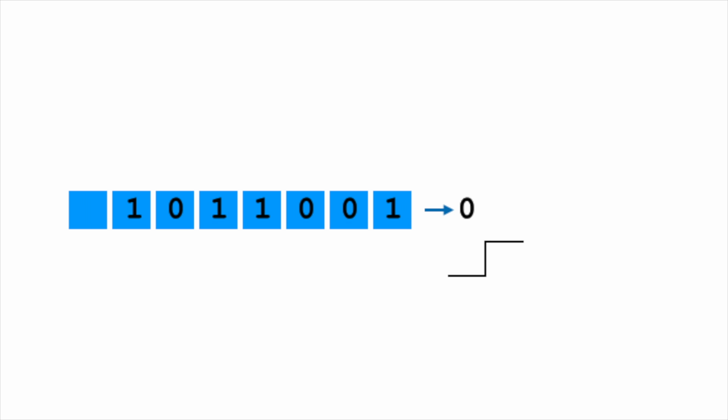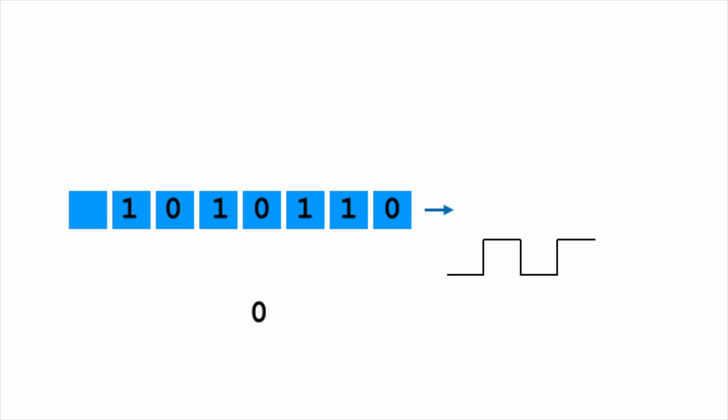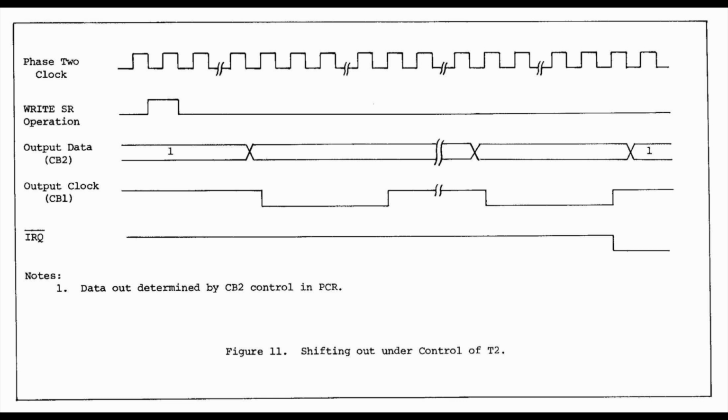The frequency of output is governed by clock T2. So the programmer has to set the T2 clock corresponding to note frequency, the number of rotation cycles corresponding to note duration, and the pattern of 8 bits corresponding to the shape of the pulse train. The moment the 8 bits are uploaded to the VIA chip, rotation starts and the CPU is free to do something else.